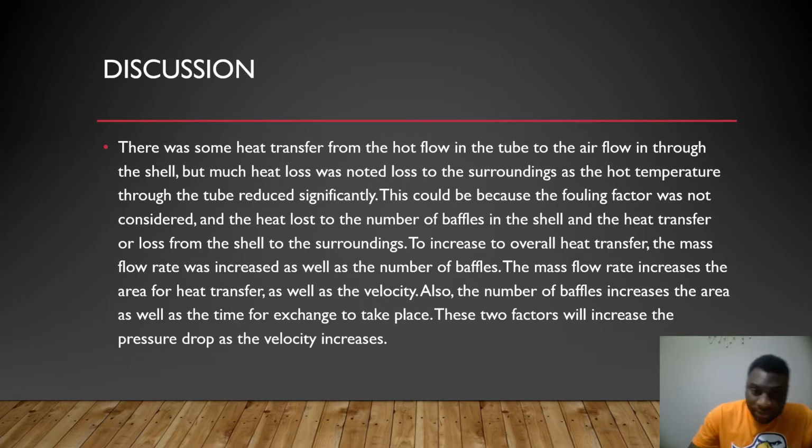To increase the overall heat transfer, a few things were noted from the calculation. The mass flow rate needs to be increased, as well as the number of baffles. The number of baffles increases the number of passages, which reduces the time it takes for the cool air to flow through the passage in the shell.